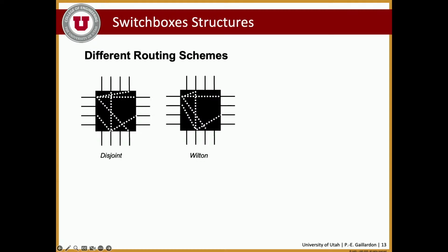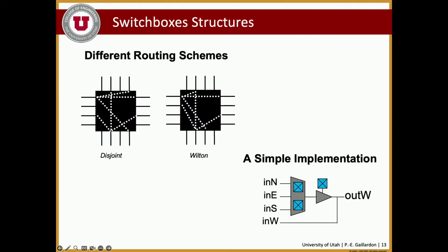In the switchbox structures, there are many different routing schemes that can be used. Disjoint pattern, Wilton pattern, so you have permutation functions that are used to calculate, based on position of your blocks, and get enough distribution, I guess, of routes. But very, very simply, everything boils down, beyond the architecture, right?